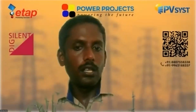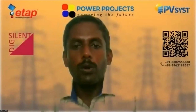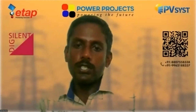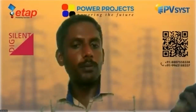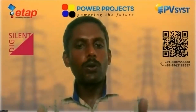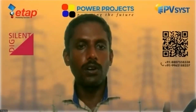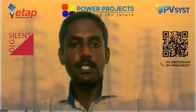Probably 20 or 30 years back, what the load dispatch center operators did was quite simple. All their sources are controllable, only the loads are uncontrollable. So whenever there is a change in the load, the frequency will automatically change, and the controllable generators with an AVR and governor will try to regulate the frequency by increasing or decreasing the generation. But now with intermittent resources, load is not the only thing changing, but also the generation, which varies with solar radiation, or with wind speed if it is a wind turbine. Then it becomes an extremely tough call to control the frequency, and load dispatch center operators are going to face that challenge.